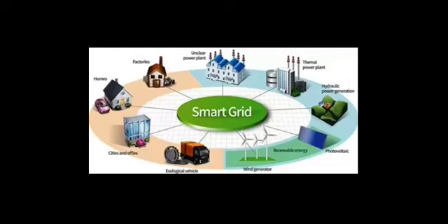Some methods for voltage control in RESs are: A. Reactive power control. RESs can contribute to voltage control by adjusting reactive power output. Wind turbines and solar inverters can be equipped with control mechanisms to regulate reactive power flow. B. Volt-VAR control. Utilizing Volt-VAR control strategies can help regulate voltage levels by adjusting the reactive power output of renewable sources based on the voltage measurements at various points in the grid.